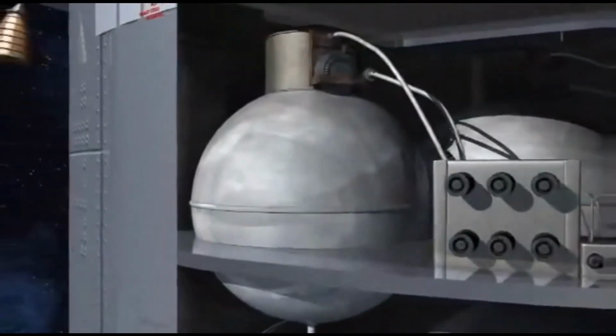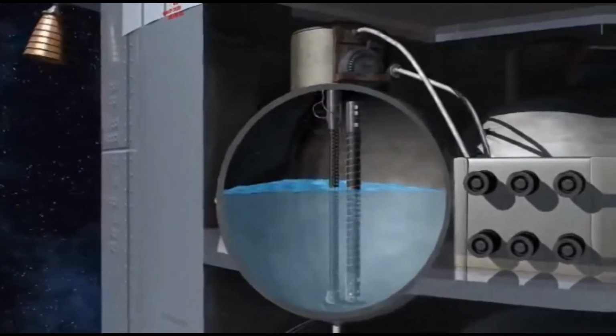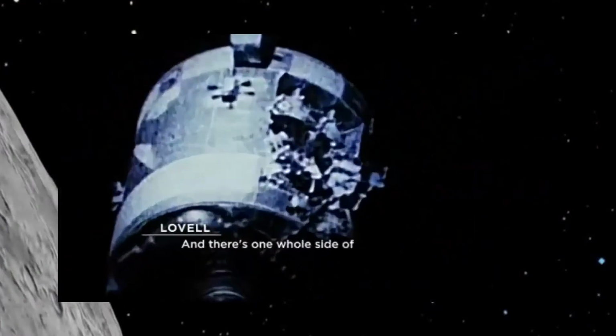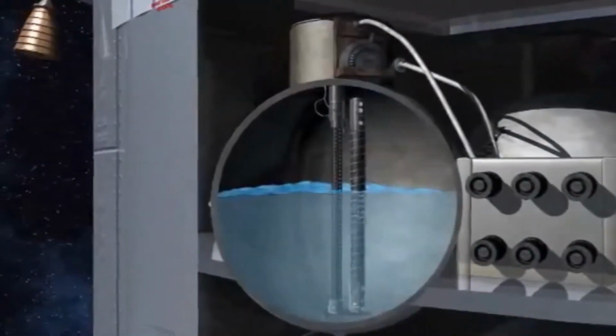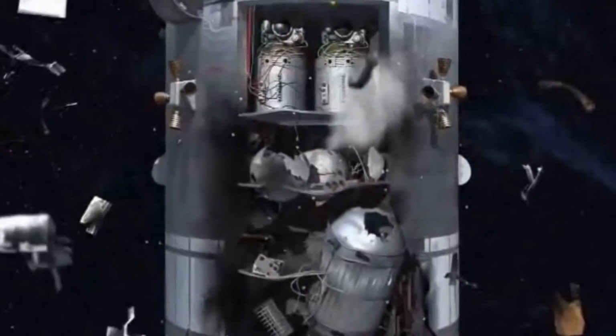And if it seems NASA was stretching its navigation technique a little, the Apollo 13 incident was another story altogether. Theatrics at its best. On April 13, 1970, Apollo 13 had an oxygen tank explosion in the service module while docked with the LM en route to the moon. Although technically it was an electrical fire that caused an overpressurization and rupture in oxygen tank number 2, which damaged oxygen tank number 1. However, the overpressurization was enough to blow the side panel off the service module SM.